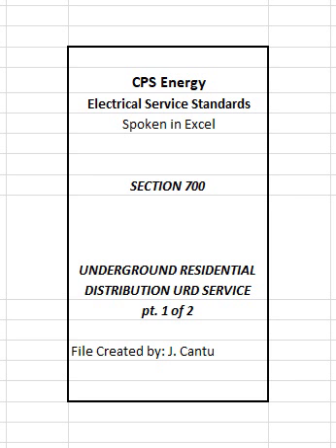Exception. With prior CPS Energy approval, customer may elect to use contractors to install trenching and conduits. The contractor shall coordinate with the CPS Energy customer service representative to have all necessary inspections before covering or pouring, refer to helpful numbers listed on the inside front cover page. Note: where overhead lines are installed along a property that is located in a URD system, service laterals may be supplied from distribution poles.